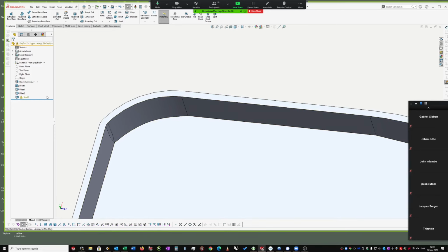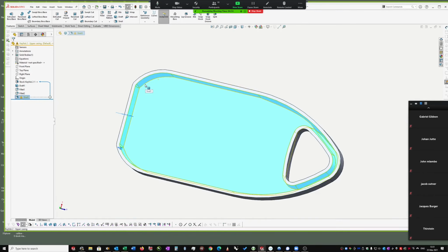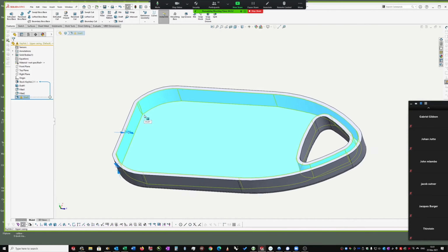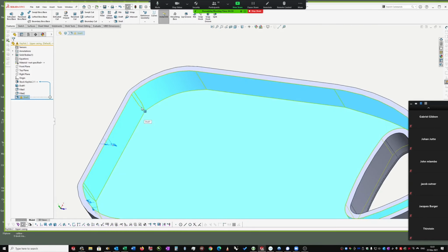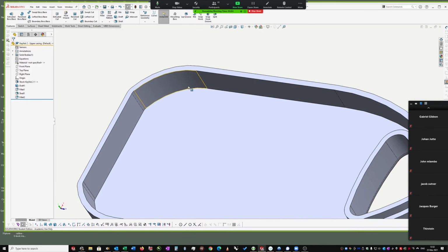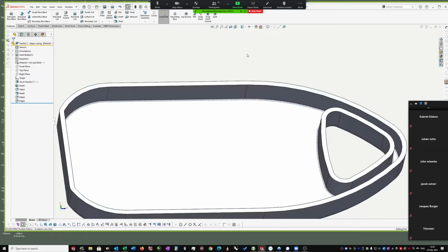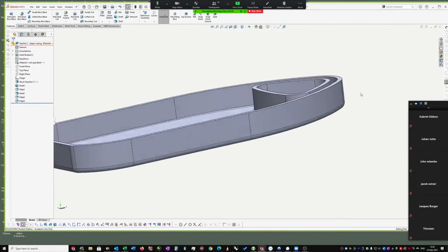fillet, you'll see the shell doesn't like this because there's now an error. That fillet is too much of a problem in trying to fillet in these places here. So I'm going to reverse that, go Control Z, and then if I want to introduce a fillet in here, a very small one, I can. So let's make that 0.2. Alright, so that's done it on the whole face.